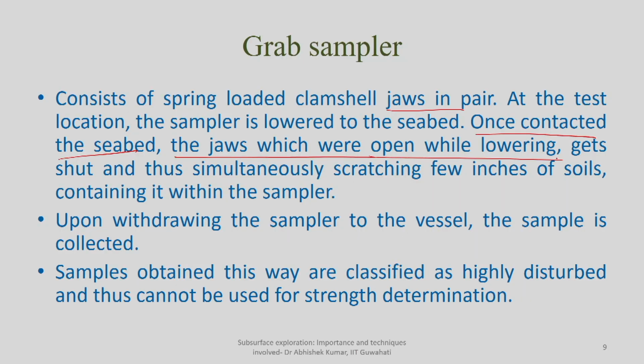While shutting, because these have teeth at the lower end, they scratch the material, simultaneously scratching a few inches, or depending upon the seabed characteristic, even half a meter or more, of the seabed material. And because it is locked from the bottom, there is no place the soil sample can go. You can bring the sampler onto the surface.